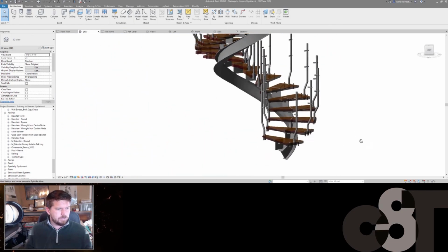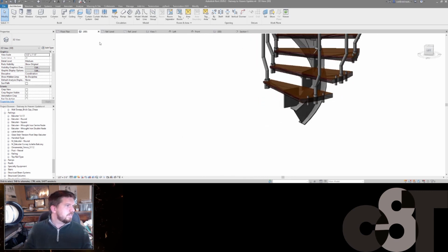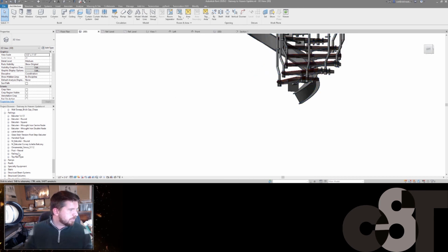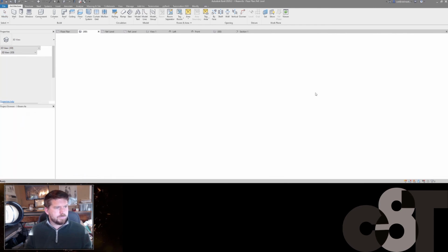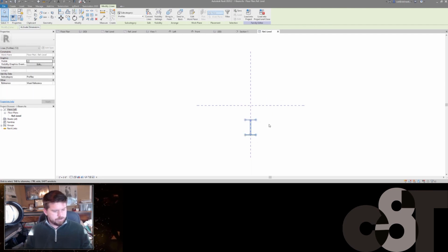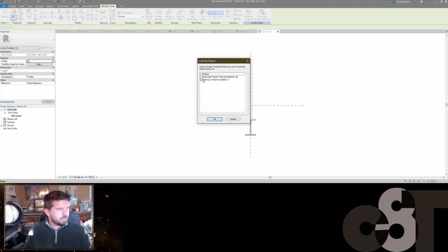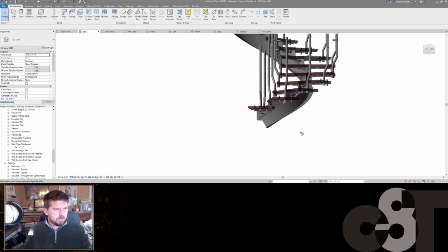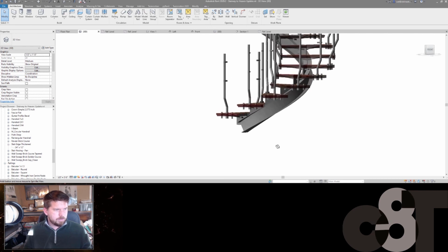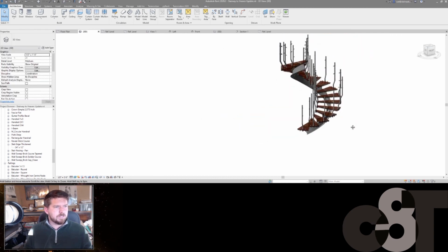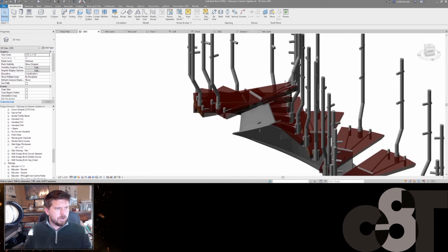Right, and we're starting to look like something fun is going on. I think for the other half of this, I'm going to bring the I-beam profile up. So let's go find our I-beam profile and edit this. And then we're just going to bring this up 100 millimeters. All right, load this back into the project. And override existing. And it's pretty tight. It can probably come down just a little bit, but I'm okay with this. So let's go forward with this right here.